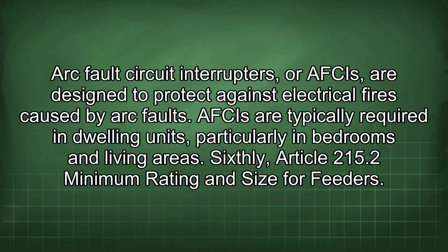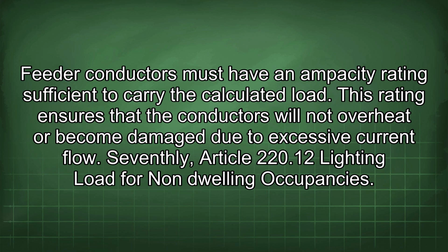Sixthly, Article 215.2 Minimum rating and size for feeders. Feeder conductors must have an ampacity rating sufficient to carry the calculated load. This rating ensures that the conductors will not overheat or become damaged due to excessive current flow.